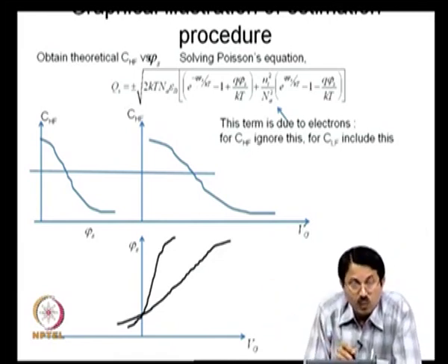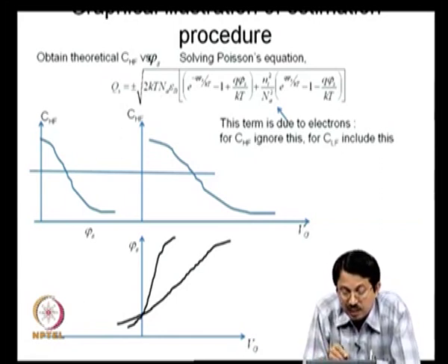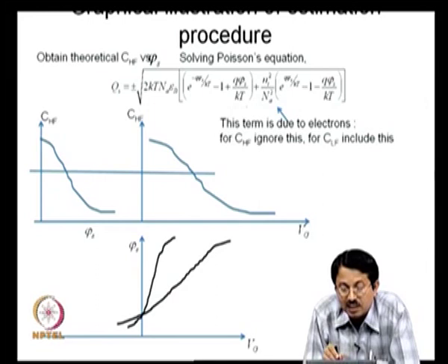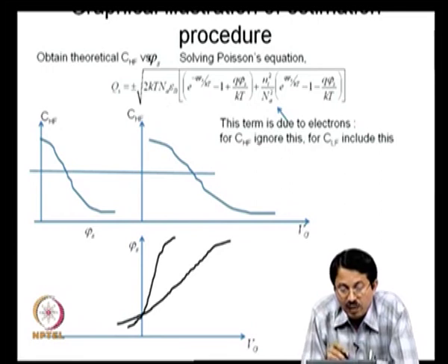Okay. So, this expression here corresponds to your whole charge and also the depletion charge, and this expression corresponds to your minority carrier charge, which is electron charge. I have already found out Na, and I know all other constants, epsilon silicon, everything.